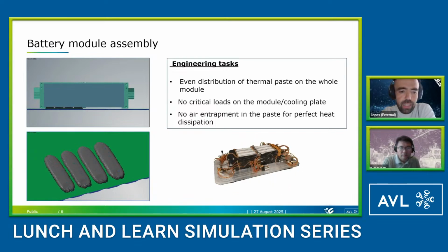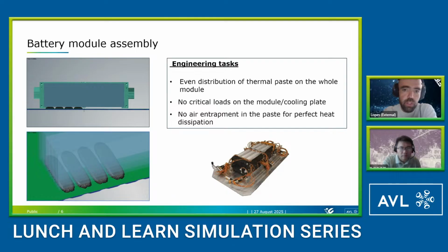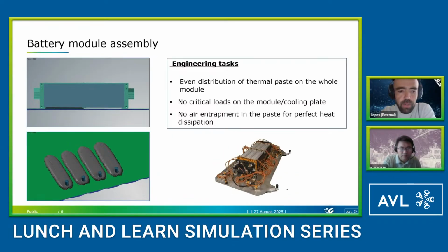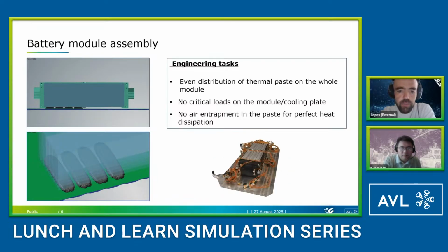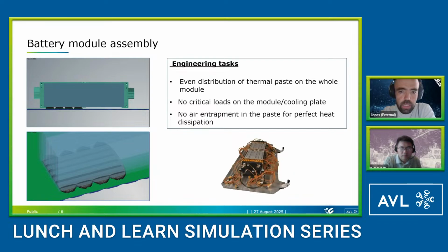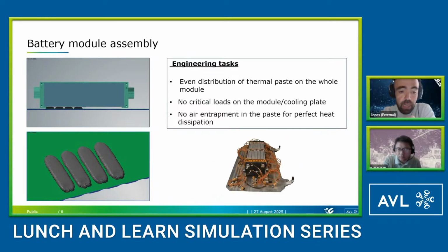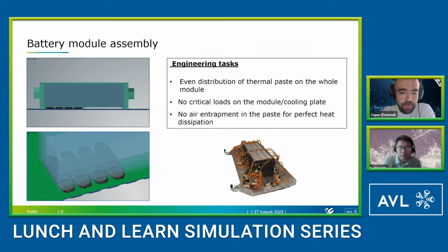And the insight that we want to get in this simulation is basically the distribution of the thermal paste on the model. We want to ensure that all of the battery is in contact with the paste and therefore in contact with the cooling plate, maximizing the heat transfer. And we also want to get insights on the loads on both the module and the cooling plate, to see whether, for example, there are some components in the battery that can stand these loads. And of course, we also want to ensure that there are no air pockets in the paste, because of course, with air, the heat transfer will be less. So we go to the next slide.